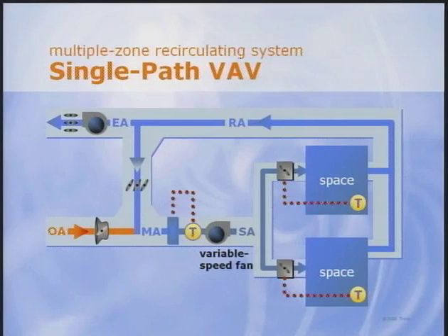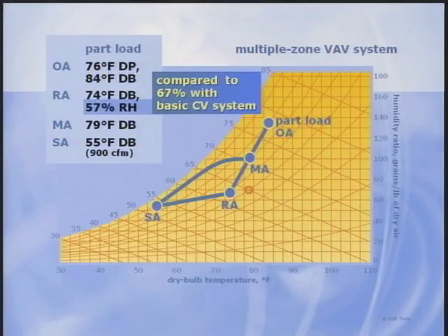An iterative cycle chart analysis at design dew point shows that as the sensible cooling load decreases and the VAV boxes reduce primary airflow, the cool, dry primary air limits zone relative humidity to about 57%. So this VAV system example also meets standard 62 without direct humidity control. Clearly, dehumidification depends on system type, configuration, and control.